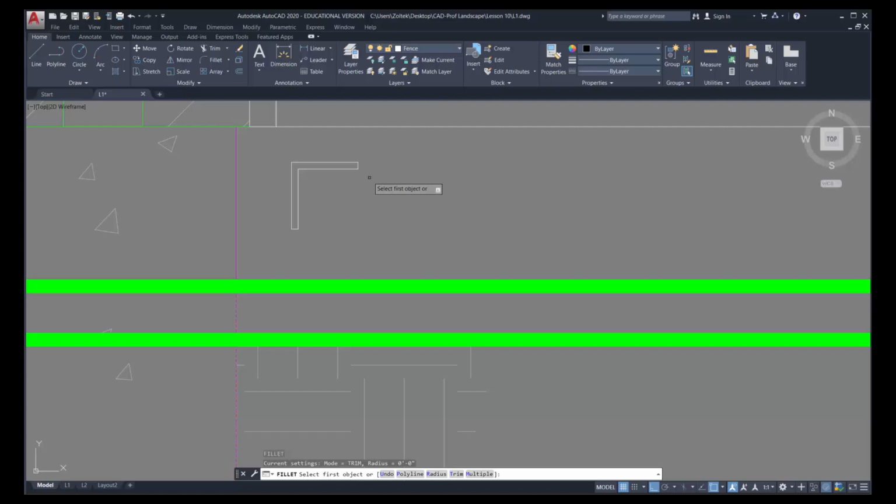So now that I've got this in place, I'm ready to draw the bolt. I will offset the measurement that's shown there at 1 1/8. That's 1.125. The top line down. Now that bolt shows that it extends 4 inches into the actual foundation wall, so I'll offset by 4, this line in.